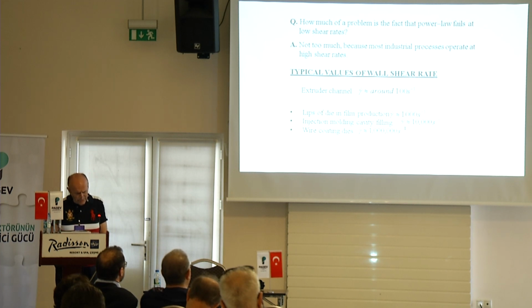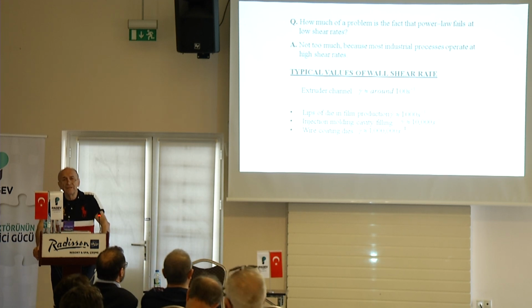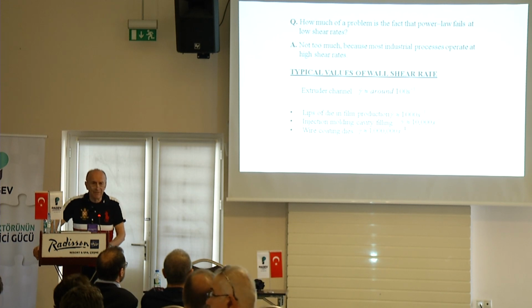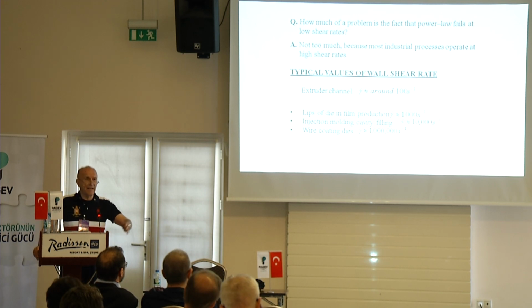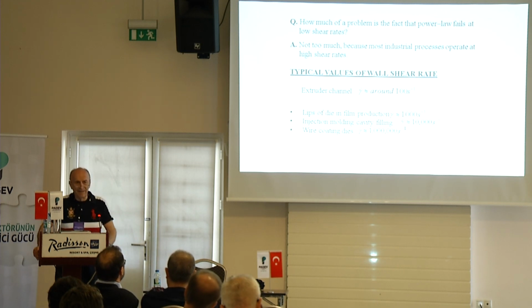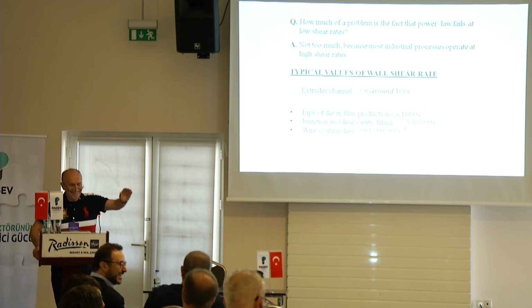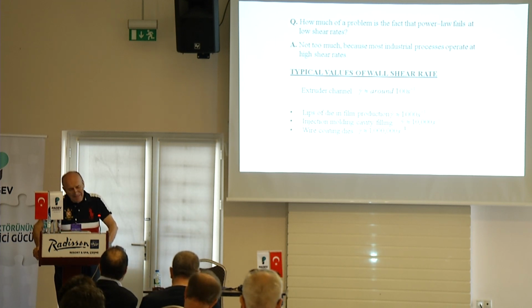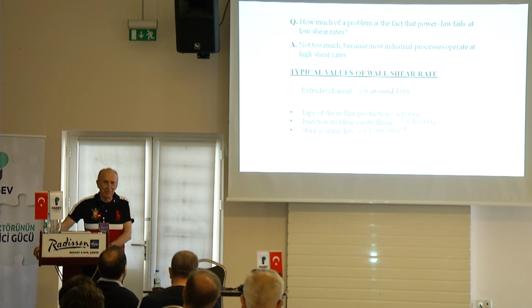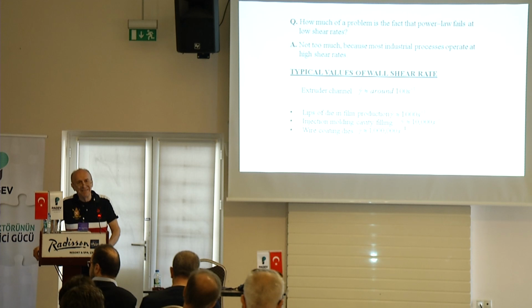And also, we should understand what sort of shear rates we have in various processes. In an extruder channel, inside an extruder, let us say an extruder that my friend Abdullah Demirci designed at Microsan in Gebze Kocaeli, the shear rate, I'm guessing, is going to be probably around 100, maybe 200 reciprocal seconds.